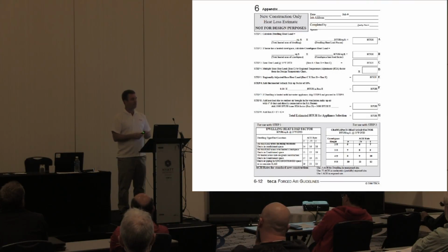But my experience has been that if somebody builds a house on the side of a hill with a huge view and puts a pile of windows in there, you can't use one heating control for that whole house. That room will have way too big a heat gain and way too big a heat loss for you to heat the downstairs back bedroom at the same time as that room. One of two things will happen depending on the season. It'll be either way too cold in that corner or way too hot in that corner when you try to compensate for that.